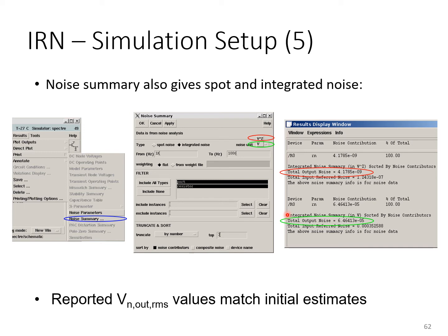So if you want to make a change to the design that will have a significant impact on its noise performance, you really want to focus your effort on those particular transistors, and the simulator will help point you to which transistors are dominating the output noise. Although hopefully, as the designer, you would already have some intuition as to which transistors those might be.